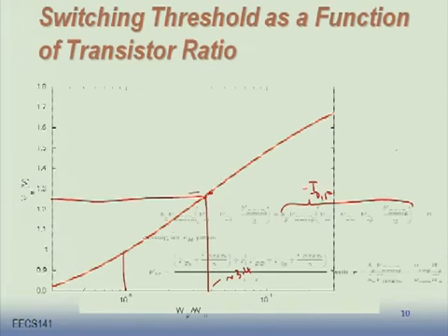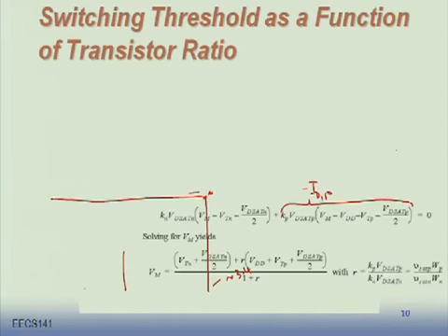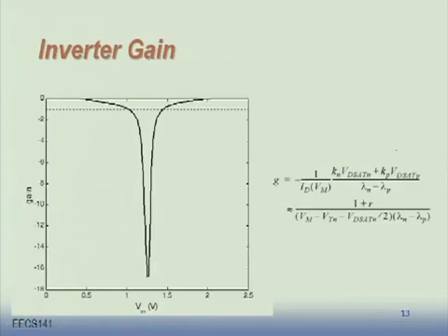Something has gone wild with this. Yeah, so by differentiating this, you can get that. And this is not an analytically solved plot. This is showing a plot of gain versus V in obtained through SPICE. So you find out that the maximum gain of this inverter happens around the switching point, and it's around 16 in absolute value. And VIL and VIH points correspond to these two voltages where the gain intersects.